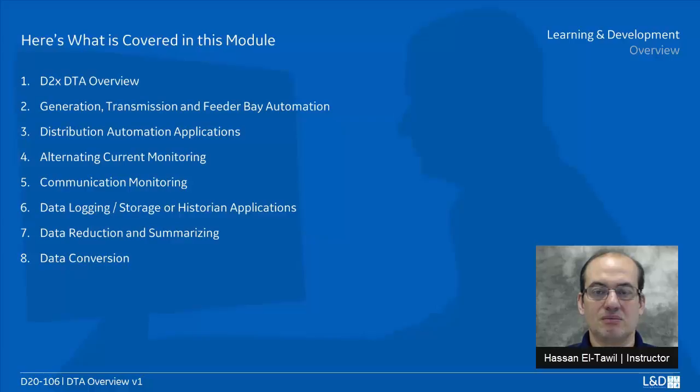That's basically what a data translation application does: it takes information from the database, changes it, and then places the information back into the database, so that, for example, the state can be converted. If a 0 is coming from the field to the device, that means it's offline, and a 1 needs to go to the master, because 1 to the master means offline. So this application would change a 0 state to a 1 state. That's basically when we convert a state.